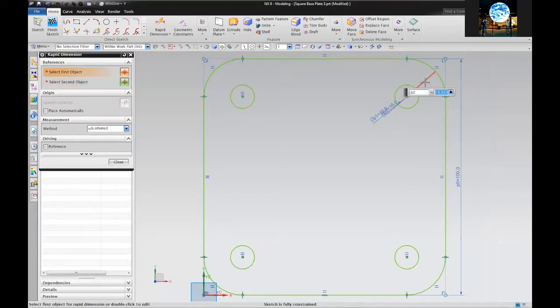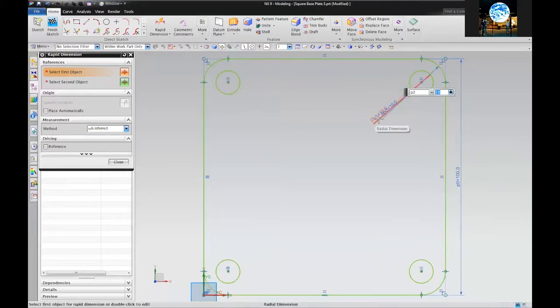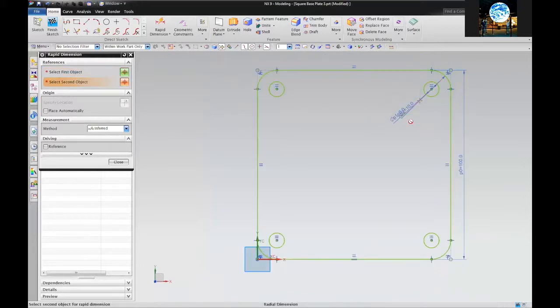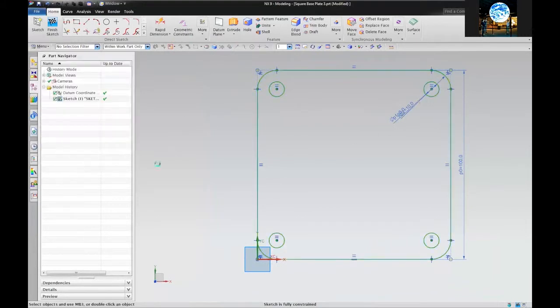Now let's set the radius of the fillet curve. And this is going to be, I think, 18. The circle was 10 millimeters. Oh, both of them are 10. Okay. Now, oh, no, one is 8. I can't really see what that is. But I'll see it once I move that out. So you see we have our radius there. The radius of the circle is 8 millimeters and the radius of the fillet is 10 millimeters. Notice that all sides are the same. Everything should be fully constrained.